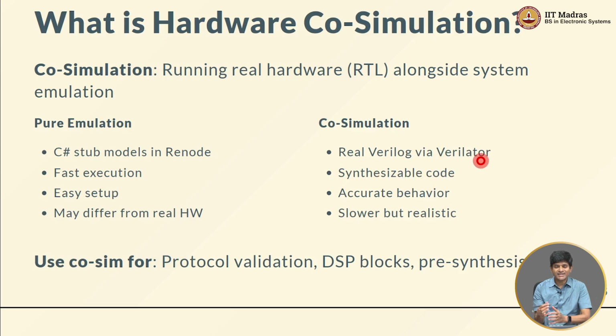Verilator has an interesting approach to simulation. It basically compiles your Verilog code into C++. You then put a wrapper around it, which is itself written in C++ in most cases, and it allows you more control than if you just try taking the basic Verilog test bench and running it. Since you are actually simulating the Verilog code that you have written, it is accurate in the sense that it is at least accurately modeling whatever RTL you have written.